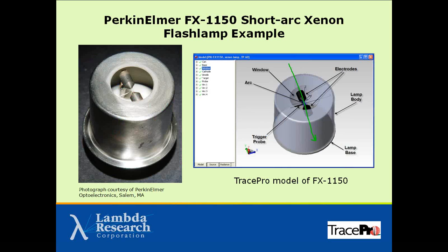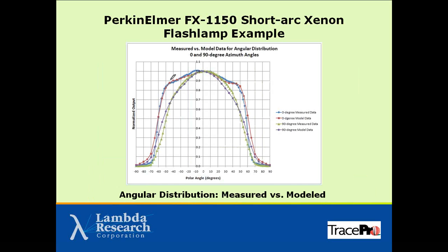So there's some shadowing due to the two electrodes. So if you just modeled this lamp without any electrodes or without any objects there, you'd be modeling something that looked more like this outer curve here, and you'd be missing the fact that in that axis across the electrodes it's actually a narrower emission. So a way you can improve your accuracy there is to have some of that structure in place.